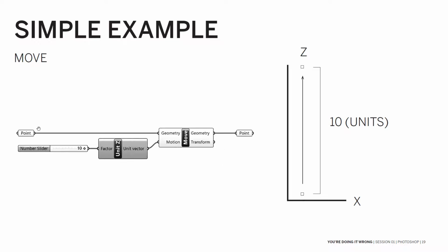So breakdown of the script, right? This is the input. This is the start. This is the initial data that's being manipulated. So we now have the what. We then have a command called move. Now the command is requiring 2 inputs to work. Now not all Grasshopper scripts require all of their inputs to be satisfied for them to work, but in this case you do need both inputs to work. And the inputs that, yes.